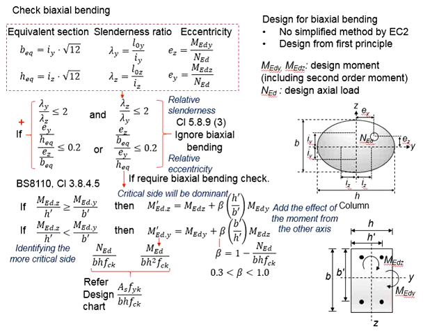Next, you need to check these 2 items. To do this, you need to get the equivalent eccentricity as well as the equivalent dimensions of the column. Let us deal with the equivalent dimensions of the column first, since it is easier. We have the equations for the equivalent section. These 2 equations are used only when the column is not in the square or rectangular shapes.